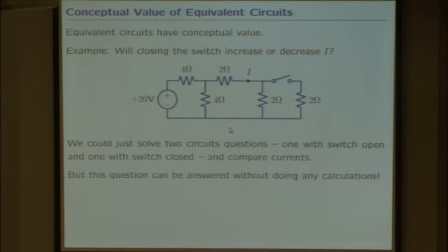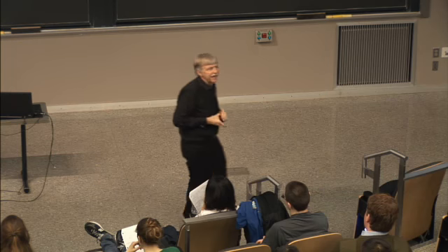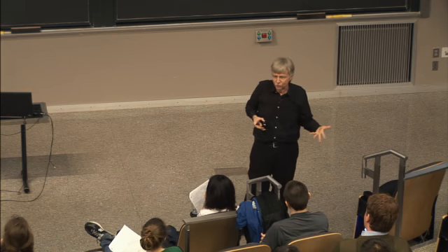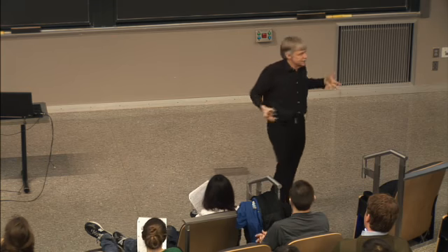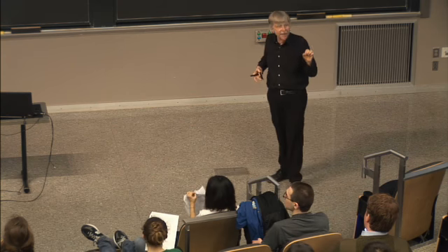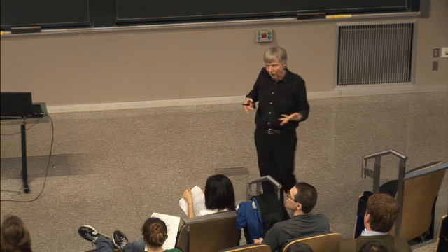That's important from a practical sense, because when you buy a part, when you buy an electronic part, they tell you how it works by telling you the Thevenin equivalent, or the Norton equivalent, or whatever is the easy way to think about it. So there's a practical reason when you buy an op-amp, they tell you how good the op-amp is by telling you how big is the equivalent resistance at the output.